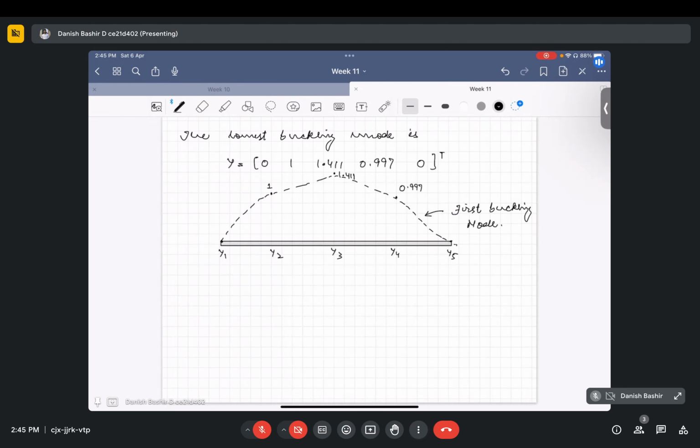Then we were seeing only two noded elements, that is lower order elements. There are higher order elements for one dimensional problems as well. So actually what we have to use for our problem is a higher number of these lower order elements to get better results. But if we use higher order elements, that is, the polynomial of our element is of higher order, quadratic, cubic, or fourth order, we can use a lower number of elements for solving our problems.